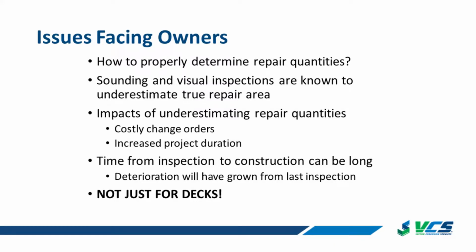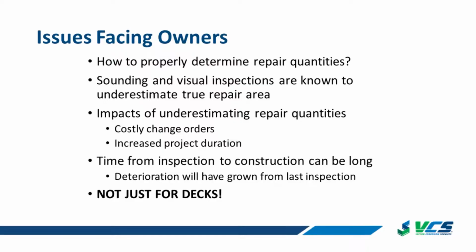We've historically, as an industry, dealt with sounding and visual inspection, but we all know that those will underestimate our true repair quantity. As we start chipping out some concrete, those patches are going to start to grow. And the impacts of underestimating these repair quantities can be very costly. Obviously we get change orders from the contractor, which can be costly, and also increased project duration. So how do we mitigate those two costly impacts?